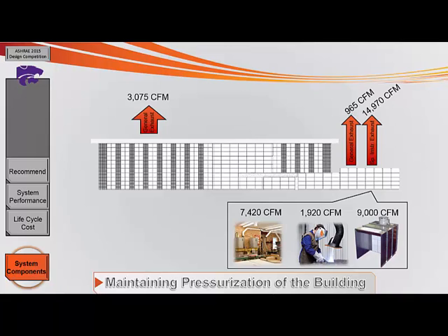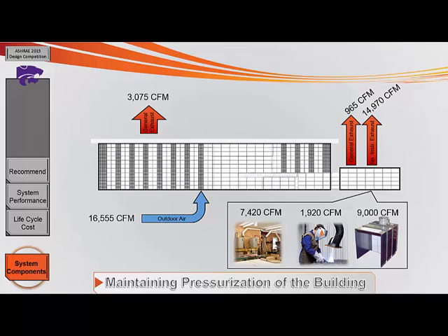To evaluate pressurization, the building is split into two parts: the main 3-story building and the special instruction space. Ventilation air will be supplied to the main building, then is distributed through transfer ducts to the special instruction space. It is imperative that this space maintains slightly negative pressure with respect to the main building to ensure that no fumes or dust particles are drawn back into the main building through the transfer ducts.